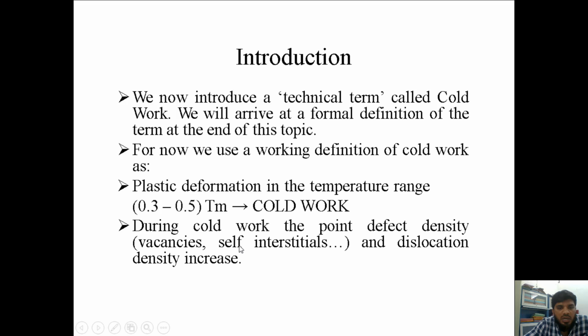If you are annealing a material, there will be changes: recovery, that is how it is going to recover its structure, and because of the structural changes there will be recrystallization. The crystal structure we have studied, the atoms in their crystal structure will try to rearrange themselves. That happens only at high temperature, whereas at low temperature it will try to recover. During this process, the material tends to go from a metastable microstructure to lower energy states. So the atoms inside go from high energy states to lower energy states.